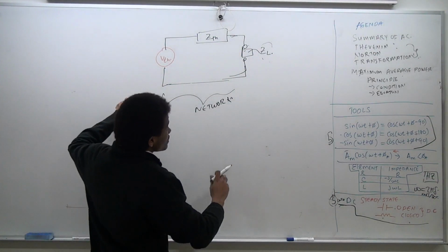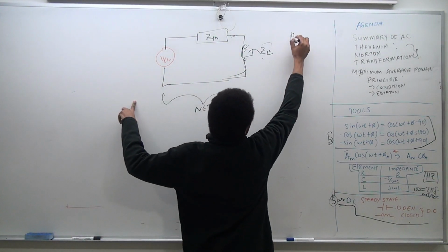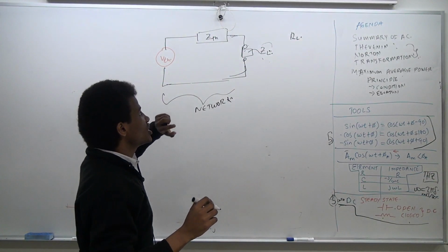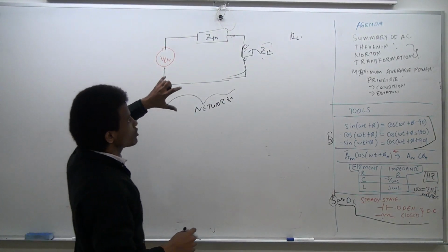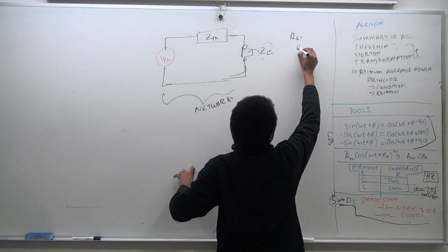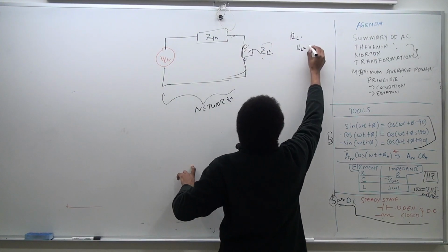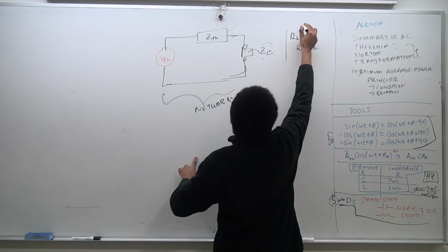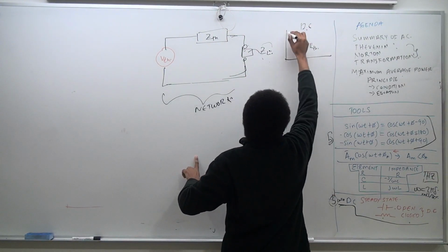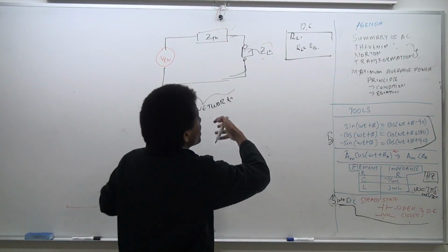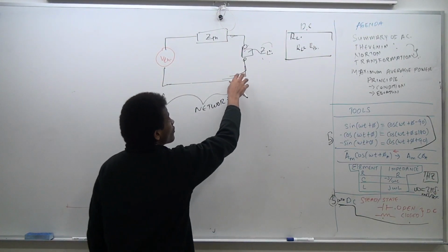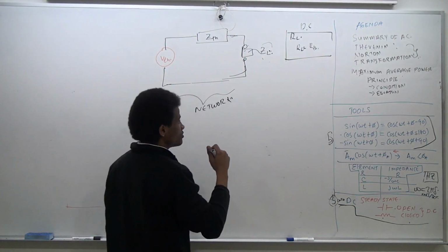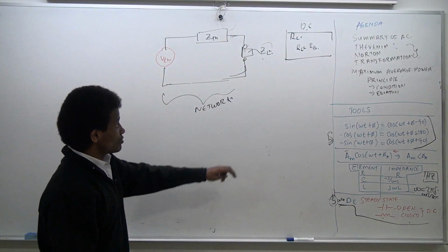Under the DC case, we're not dealing with ZL, we're dealing with RL. And we basically differentiated the optimization function with respect to the load. We realized that if our RL is equal to R Thevenin, this is under DC, this optimizes the power consumption. We could extract maximum power from the circuit, a maximum average power if we have this. And I'm using the word average because we're dealing with sinusoids. Okay, so this is what we have.